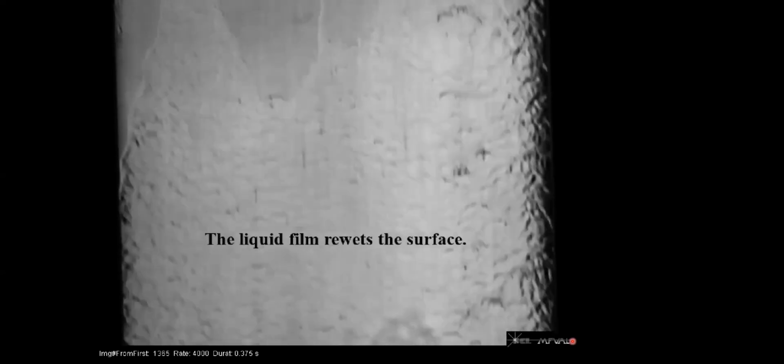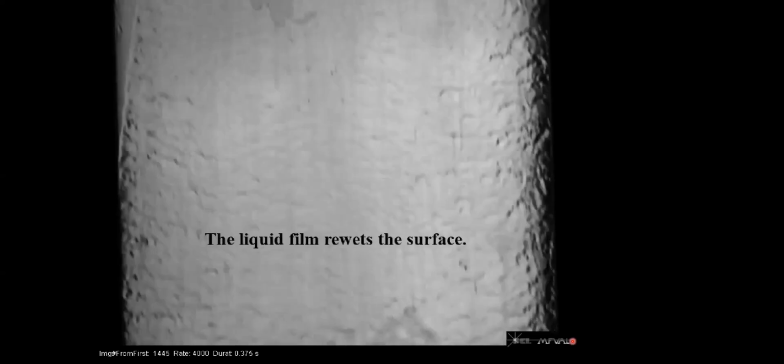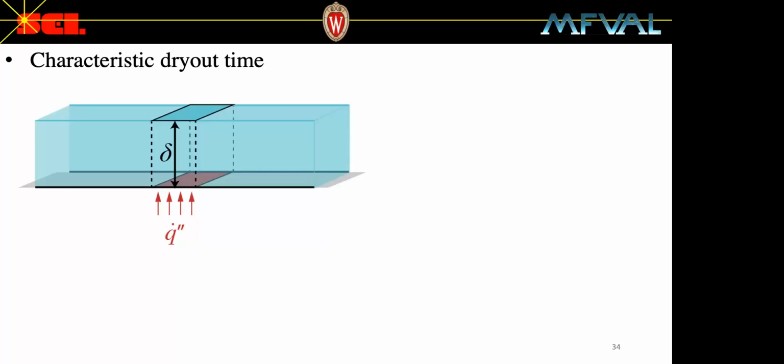So this video shows the time scales for the dryout event to occur and the re-wetting event to occur are significantly different. The re-wetting event happens very quickly and the dryout event takes some time. Through this analysis, we've observed that the velocity of the fluid in the wake of a wave is also small relative to that of a disturbance wave, and that the re-wetting process occurs on timescales that are much smaller than the drying process.